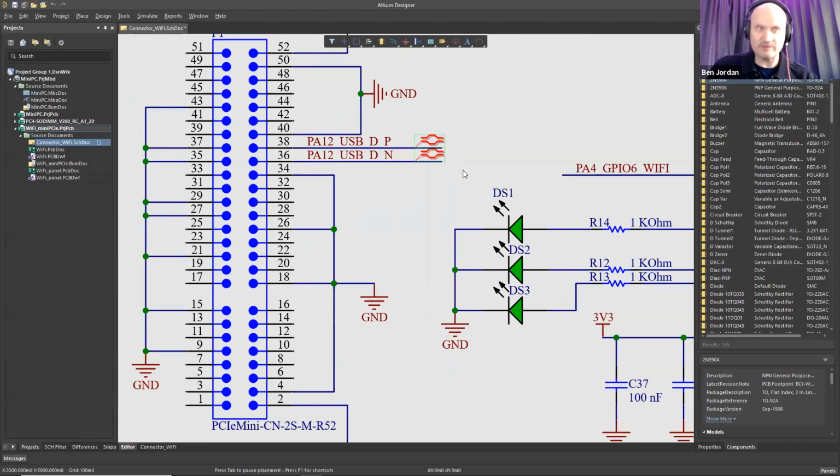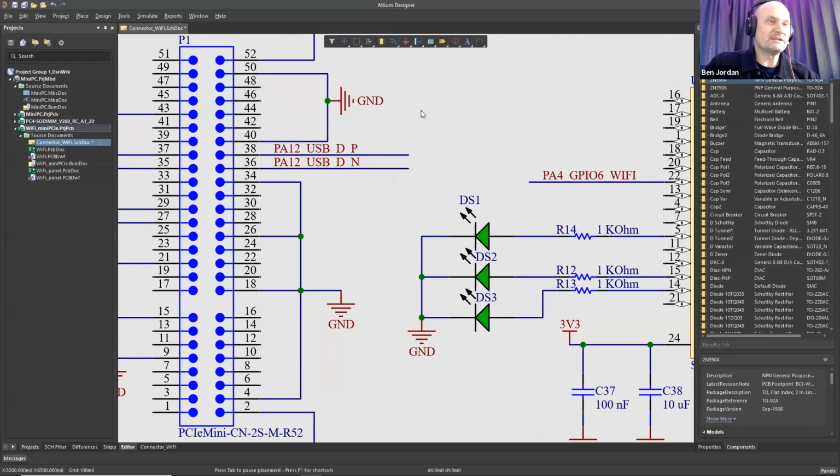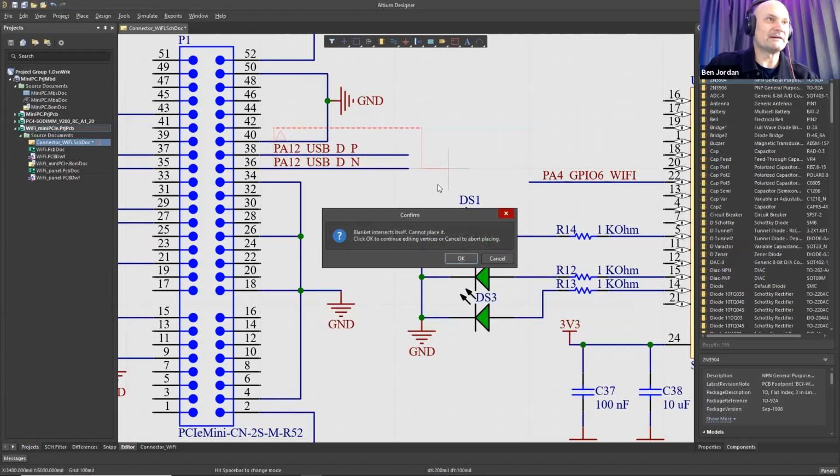If you have more than one net and they're all going to be differential pairs, let's say you have a whole bus of diff pairs, maybe an LVDS bus with 8 differential pairs or something like that, and you've named them all with the _Ns and _Ps, but you want to add that directive to all of them. You can do that using what's called a blanket, and this is where you place this blanket around those.